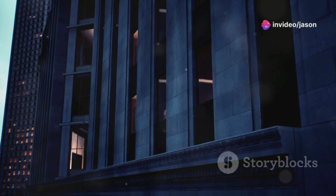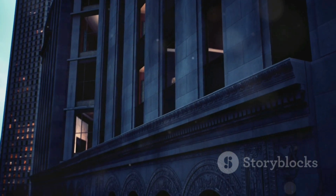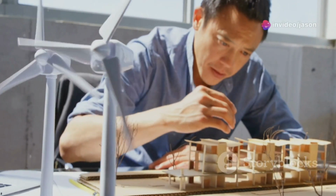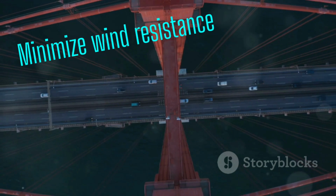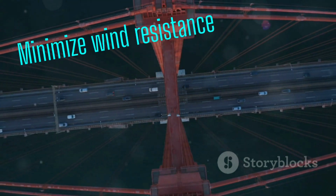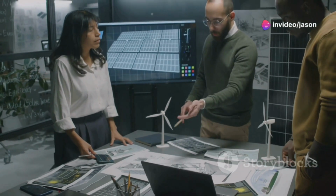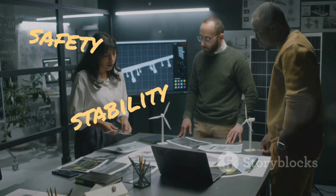For example, tall buildings are often designed with a tapered shape, narrowing towards the top. These shapes help to reduce the wind load on the structures by allowing wind to flow smoothly around it. Bridges, too, are designed with aerodynamics in mind. The shape of the bridge deck and the design of its supporting towers are carefully considered to minimize wind resistance and prevent any instability. Wind tunnels and computer models help engineers analyze how wind will interact with different designs, allowing them to optimize structures for safety, stability, and longevity.